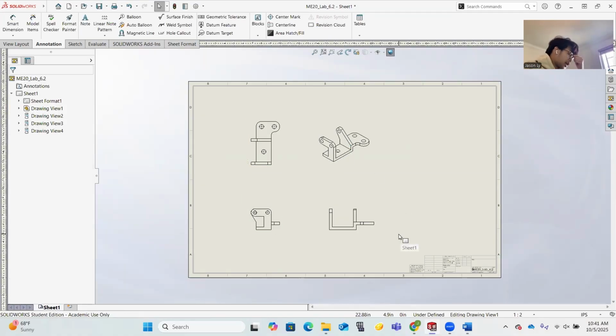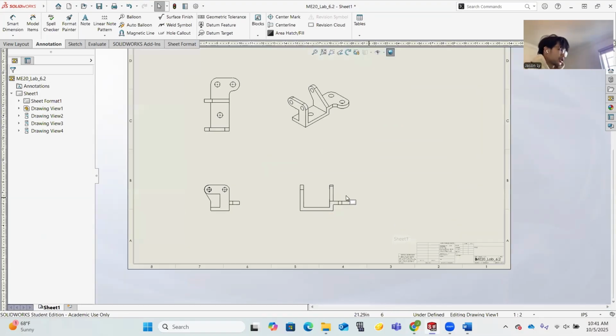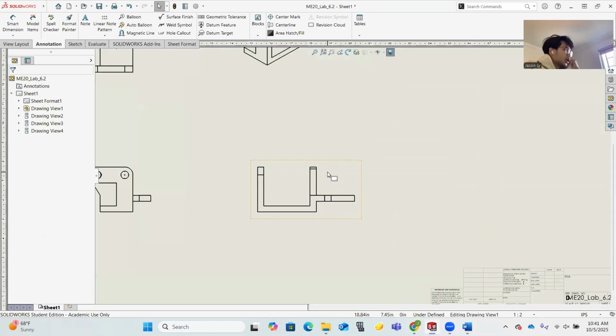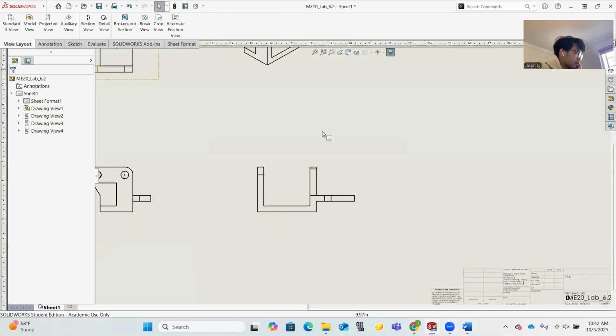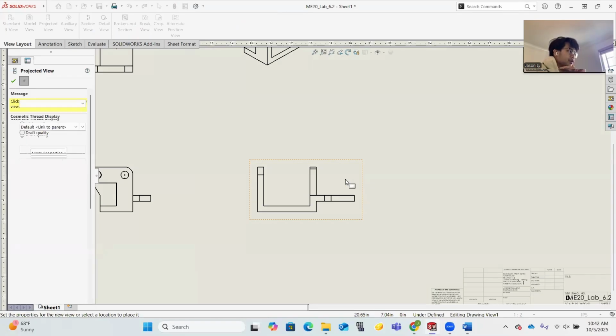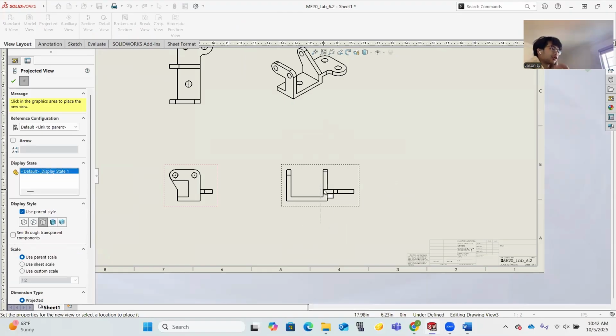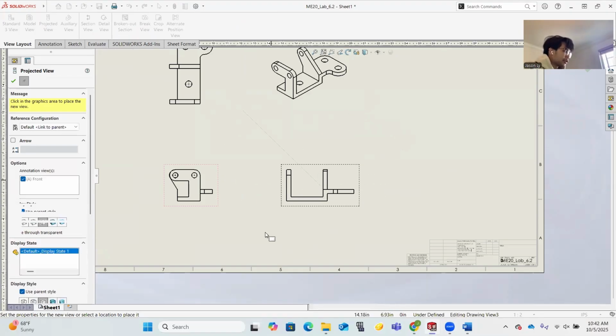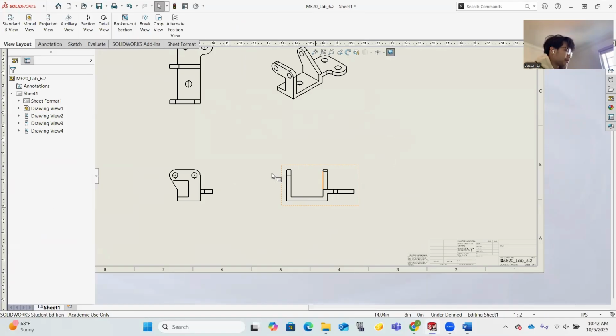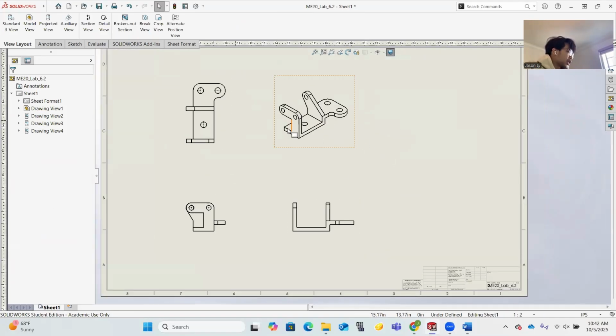And let's say one of you guys messed up your orientation when you were drawing your part initially, and this ended up being your front view. That's fine, right? We should practice doing it in the correct orientation, but if you do that accidentally, that's fine. To fix that, you can go to project view. Once you place it, click on the view you want, and same thing, move it in the direction you want it in. And then that gives you the orientation of, this is essentially your front face now, right? And you can make it go top, right, left, bottom, and put it in the ISO view you need. So in that case, you can do that. But since it's already correct, you don't need to change that.